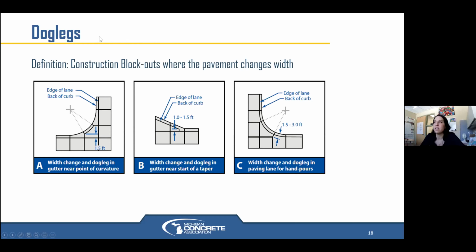If you have structures that you need to meet, and again, we'll show you some practical applications of this, we want you to be able to adjust for those structures. So we're not just jointing a pattern because that's the way we're supposed to joint, 6 foot all the way across and all the way down, no matter what's there. We really want to make those adjustments.